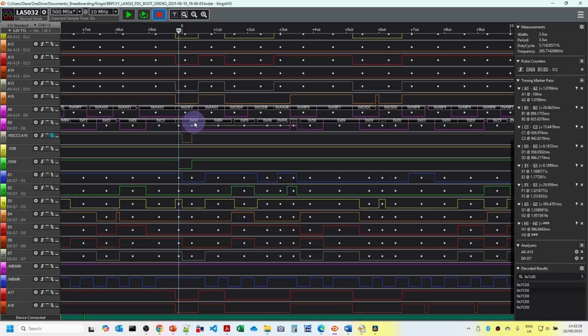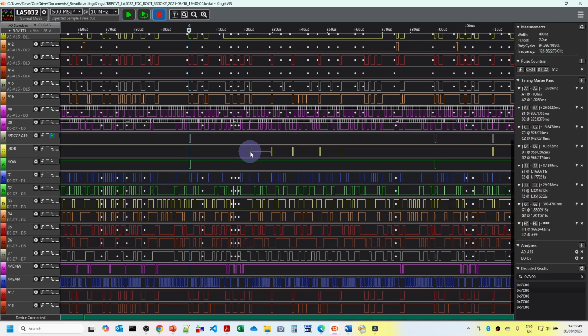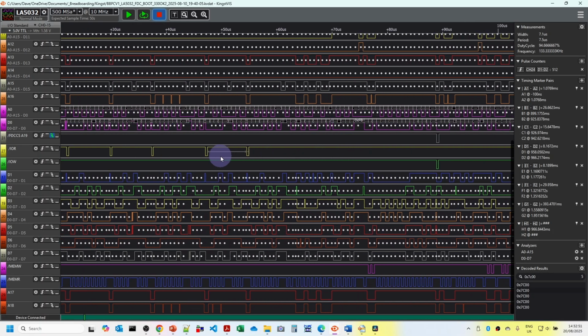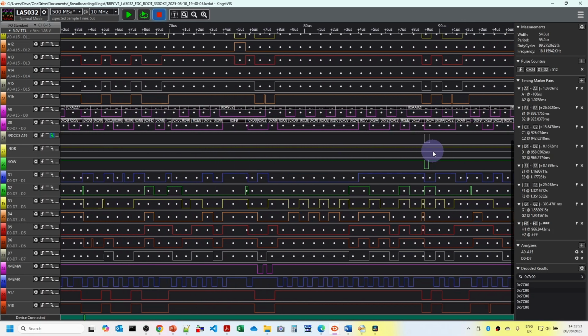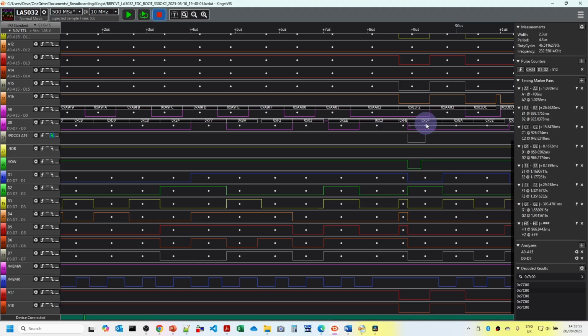the drive operations register. And what this is doing here is starting the reset of the floppy disk controller by setting bit 2, or the value 4. This is cleared to 0, though, and we start the reset. We then wait for a couple of clock ticks, and then we set it back to 4, which re-enables it.